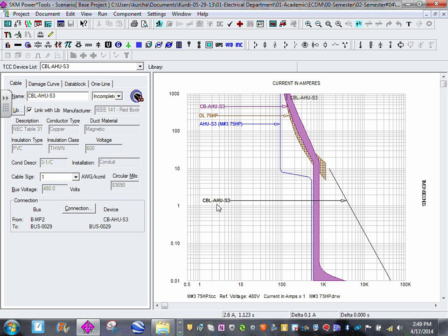One thing we also do, I was doing medium voltage today and we talked about it a little bit, is this called the damage curve for the conductor. It's not a big deal, I'm just showing it here because it's here. When we size, this will show you the conductor size that I'm using is number 1. I can't remember what it would be based on the code. If you guys go size it, that would be correct, number 1. I wasn't drinking coffee at that time. So you can oversize it here. If you go to 1 aught, you can see the curve moves up.